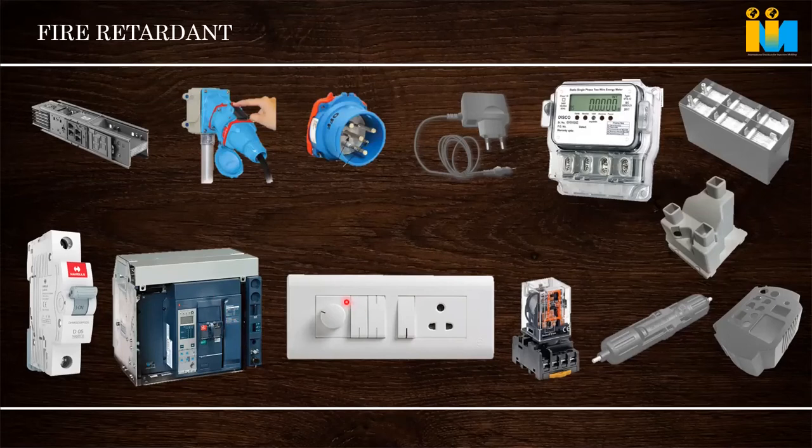And next comes the application in the switch industry. Major switch manufacturers use polycarbonate, and some use ABS also. Premium people use polycarbonate. Why? Because aesthetically it's very good. We can go for a high shine application. Polishability is very good, and polycarbonate has very good dimensional stability.